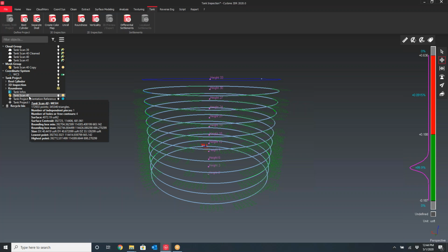I mean, so for an MS-60, yeah. If you're going to use an MS-60, you need to make sure you are using quite dense scans. It will take a little bit longer with an MS-60 regardless, but with the new MS-60, I shouldn't say it's going to take long. It's really not that bad. You need a shot to do a good tank. I would say at least every tenth by a tenth. So you need to take that into account. A tenth by a tenth on a really large structure could take a little bit of time. So I'd have a hard time calculating the field work because every tank's going to be different.